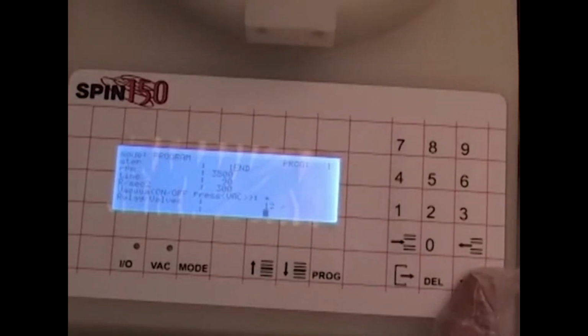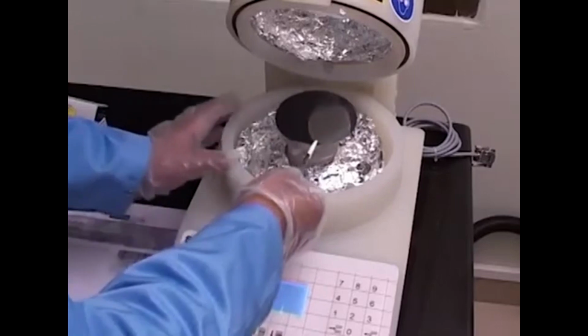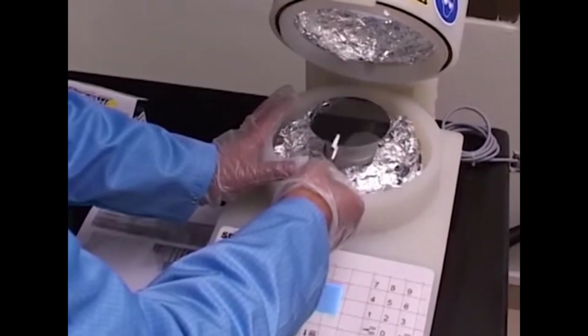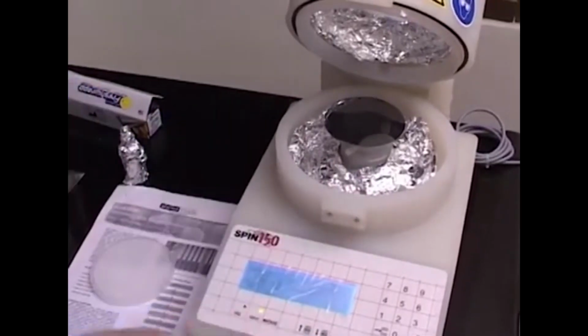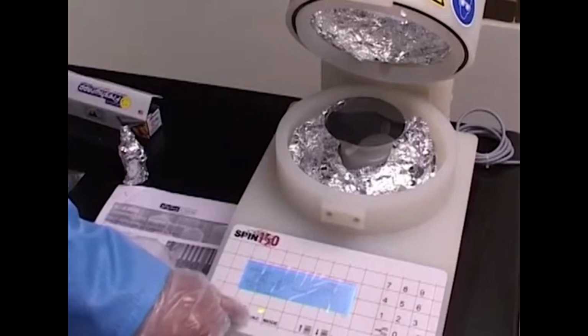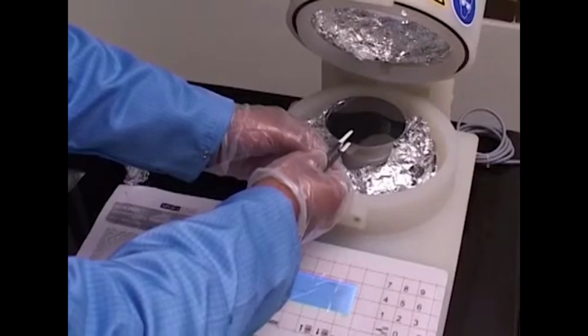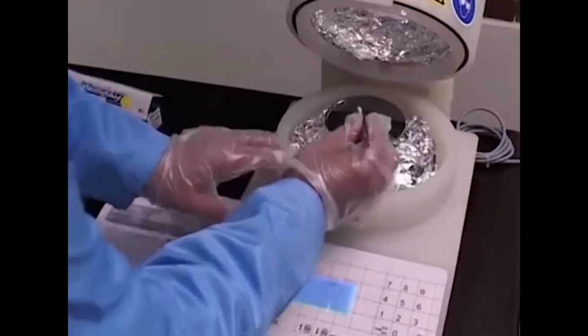All we need to do now is put the wafer back onto the spinning stage, after which we will do the run operation. So I am going to load the wafer onto the spin table, and we also have to see whether the wafer is centered, which I will do a little bit later. I just turn on the vacuum. You can see the green light appearing here, which means that the wafer is now firmly held to the surface and clamped firmly onto the spin table.